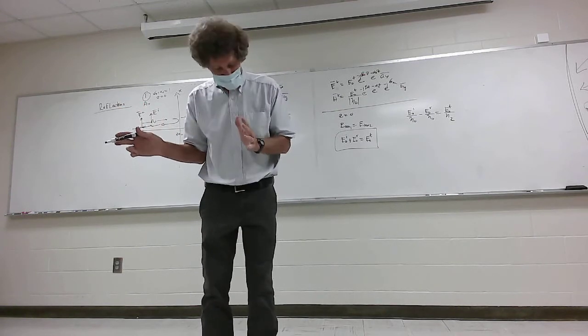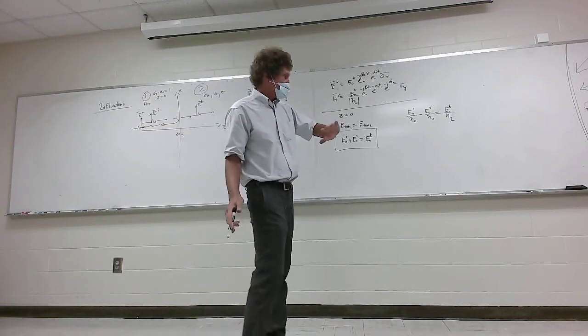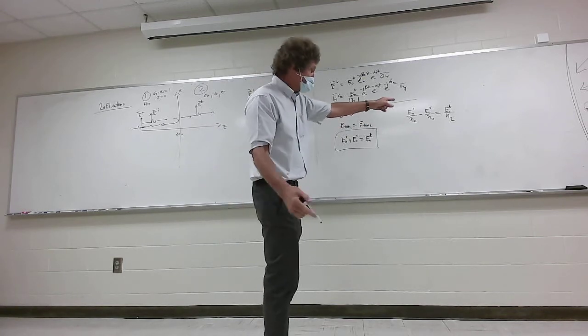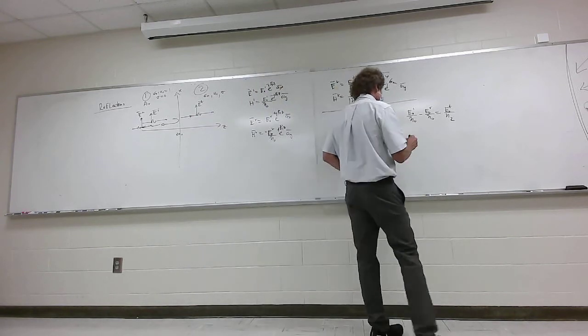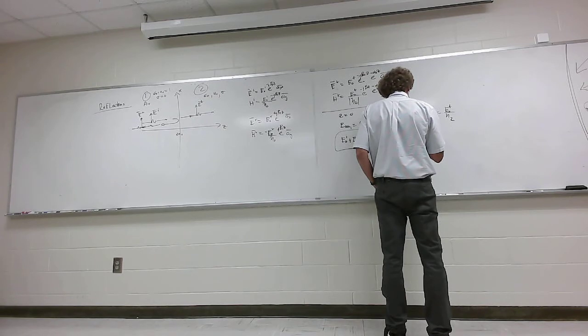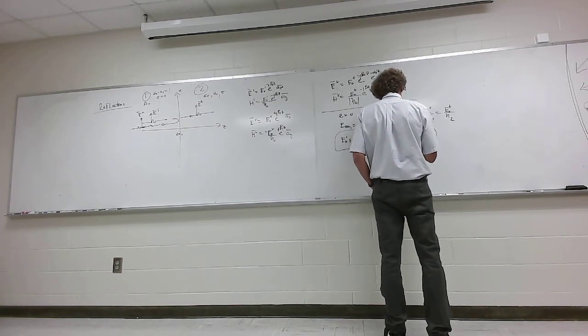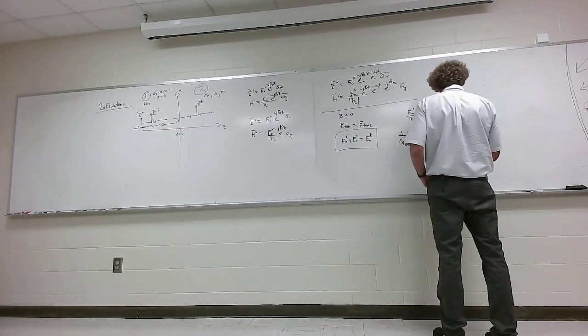All right. Now, I'm still watching my clock here. And when I do that, because I've equated these things, see that eta transmitted there? I stick in this right here, and I get E naught incident minus E naught reflected times 1 over eta naught is equal to, and then here it's going to be E naught incident plus E naught reflected over eta 2.